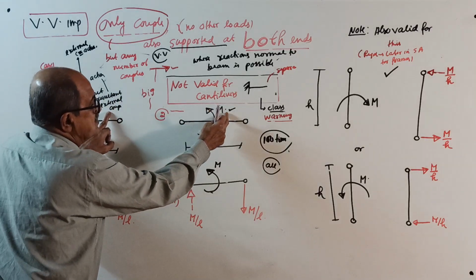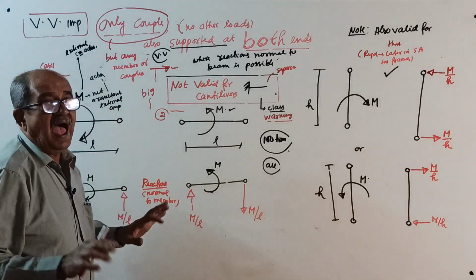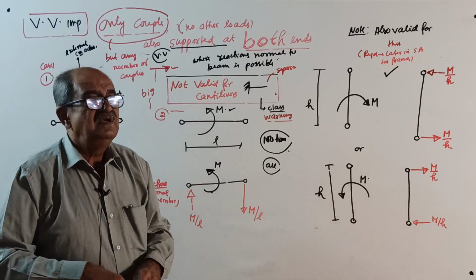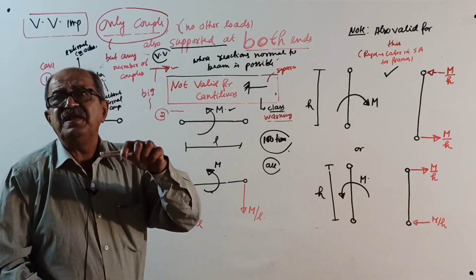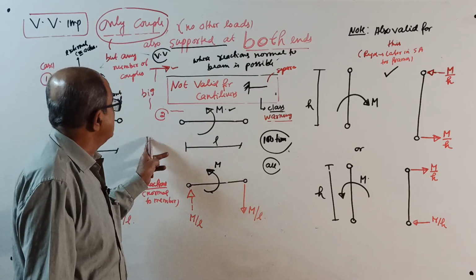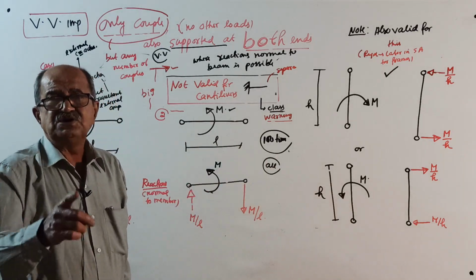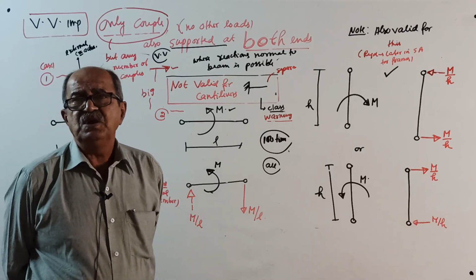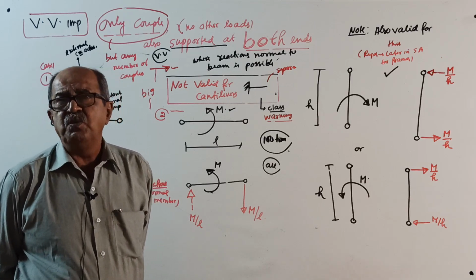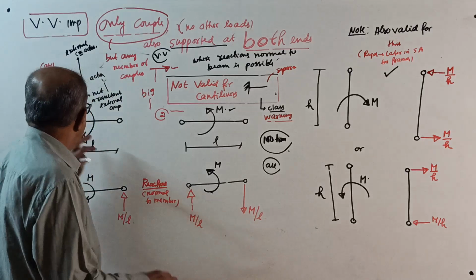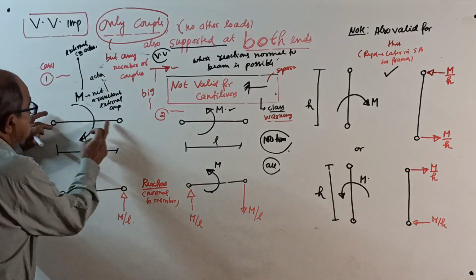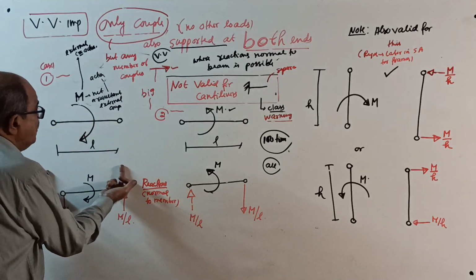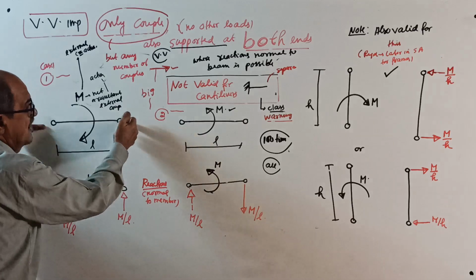External, you are right here also. That is actually action. See, it is external, it is action. Now for the action, you require reaction. We are concerned about reaction. First of all, remember, action and reactions are equal in magnitude but opposite in direction. Therefore, now start. You take both pin. I already told you, both pin means both supports, we want only vertical reactions. Horizontal, we are not bothered.